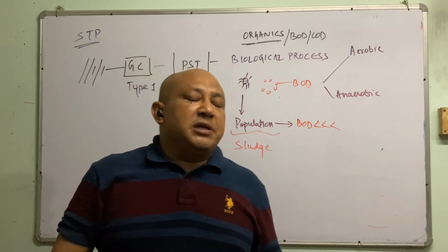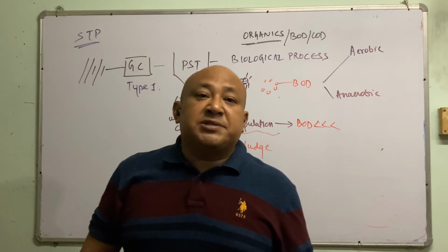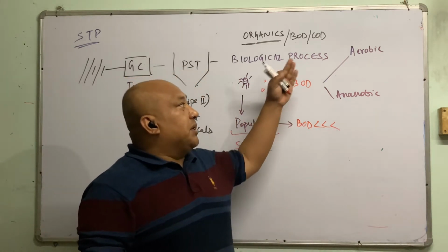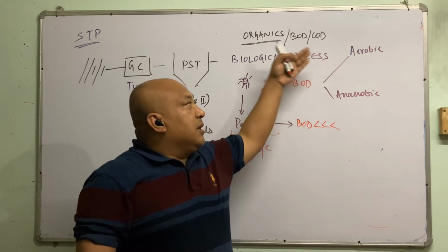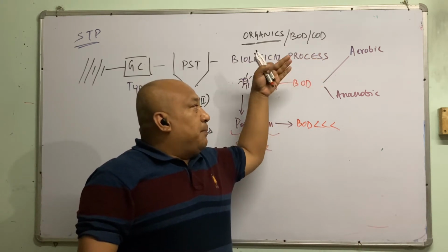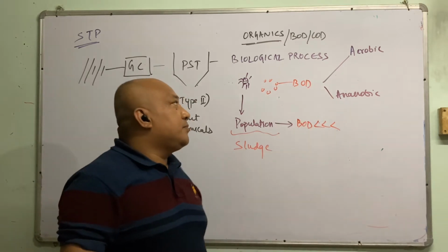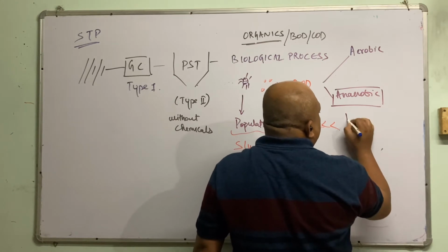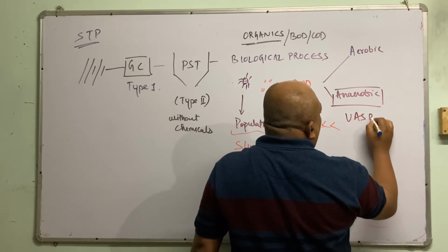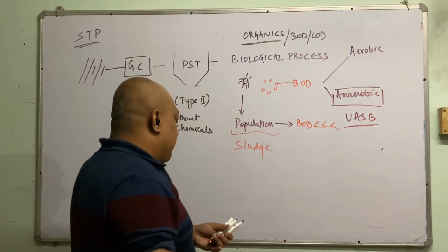But being an environmental engineering or civil engineering background, we don't have to study much about microbiology, but rather you have to focus on two things. That is the bacteria that require oxygen, aerobic, and bacteria that don't require oxygen, anaerobic. Example is the septic tank. Another example is reactors like UASB, which is not in your syllabus, only the basic concept.